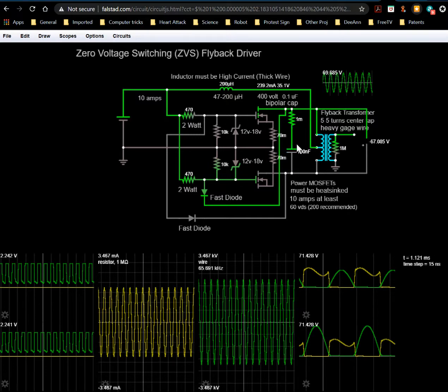you've got a terminal that is always being alternatively tied to ground, but it's changing which terminal is tied to ground, and because of that, the voltage across this capacitor is indeed negative now, and it was positive earlier, but that's because we got our meter leads positioned this way. But here the capacitor is actually being literally reversed every time this voltage changes side.